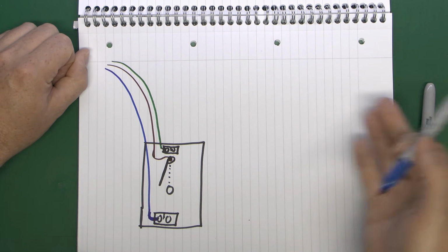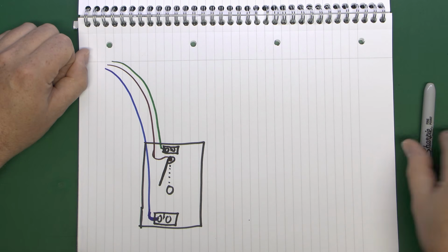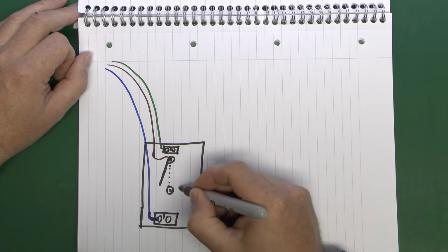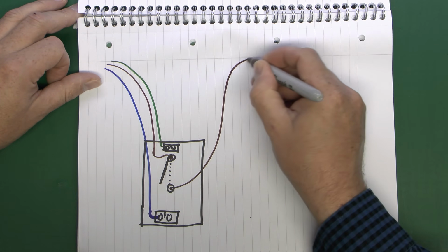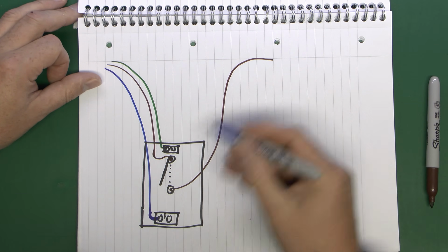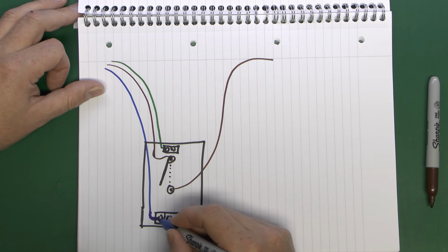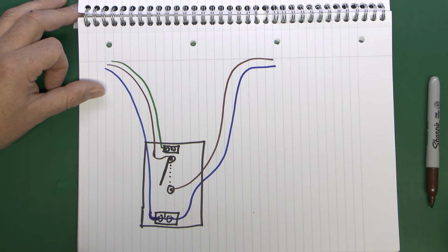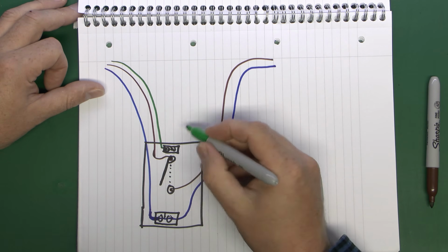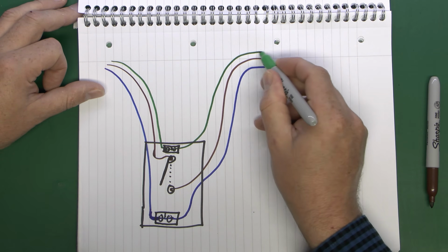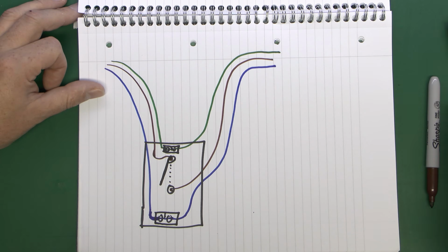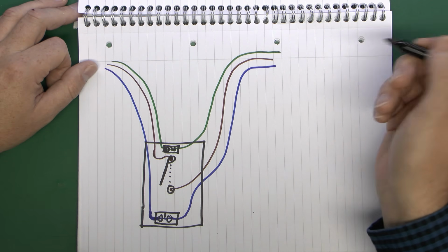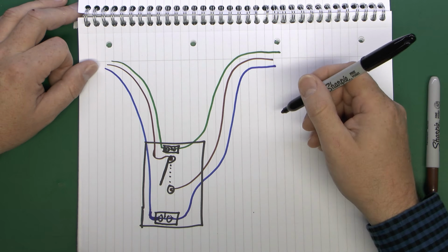Now from here, of course, we need to get power to the actual light in the middle of the room, so another cable is required. So the line will come out from the bottom of the switch, and that will go to the centre of the room. And we also need the neutral, so that comes from this terminal block here. And of course the earth will do exactly the same, so that will continue up there. And then in the centre of the room here, this is where your light will attach. So you could have a normal ceiling rose, or say a downlight, or any other kind of fitting you wanted.